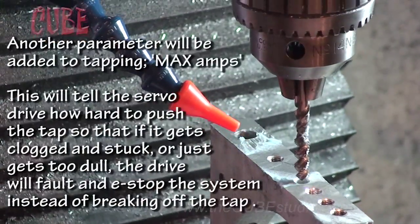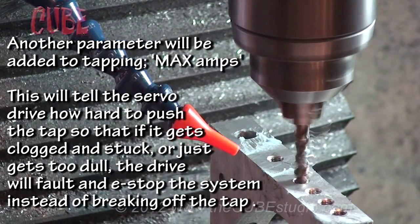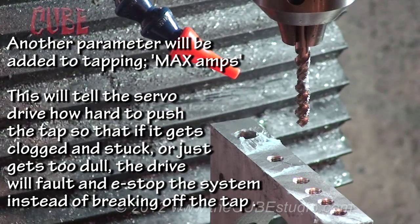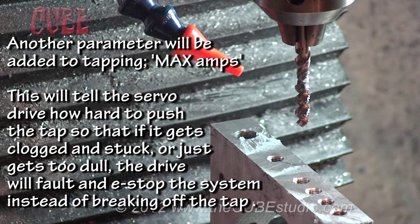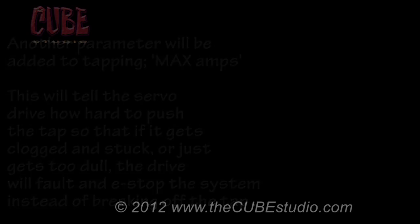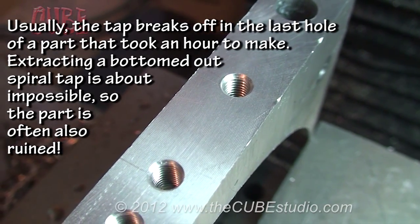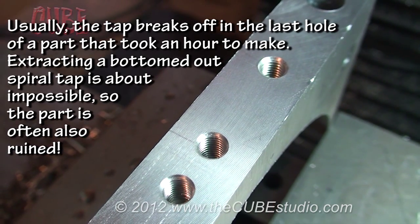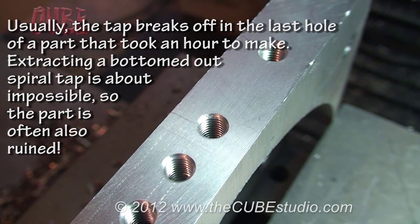Another parameter will be added to tapping: max amps. This will tell the servo drive how hard to push the tap so that if it gets clogged and stuck, or just gets too dull, the drive will fault and e-stop the system instead of breaking off the tap. Usually the tap breaks off in the last hole of a part that took an hour to make. Extracting a bottomed out spiral tap is about impossible, so the part is often also ruined.